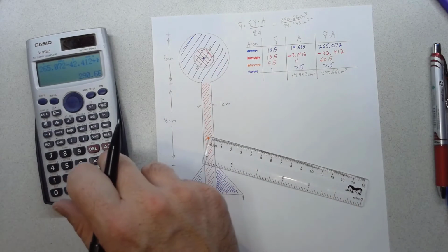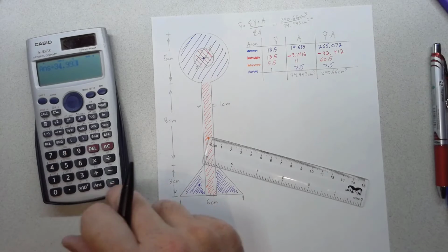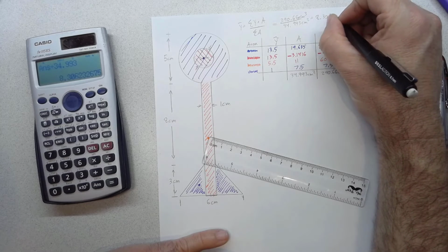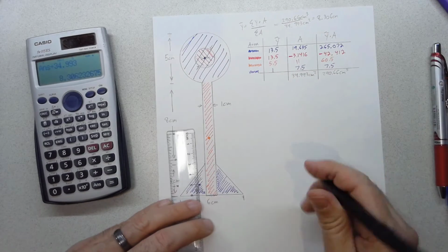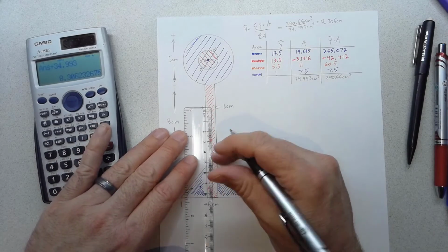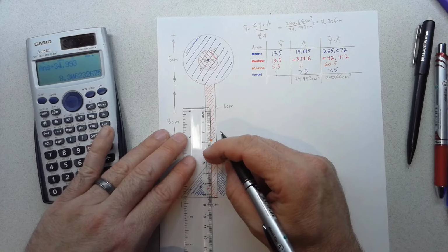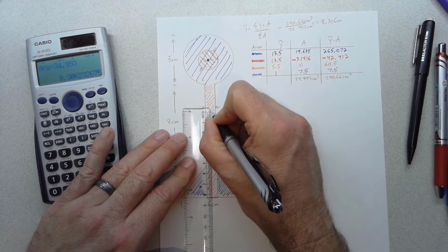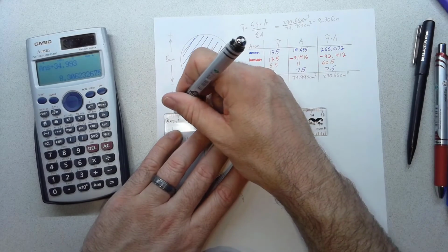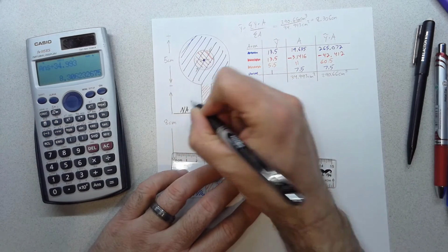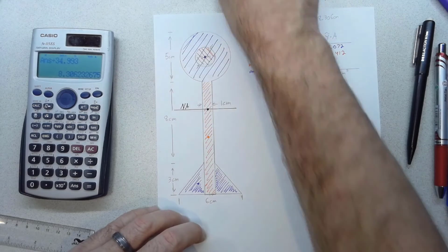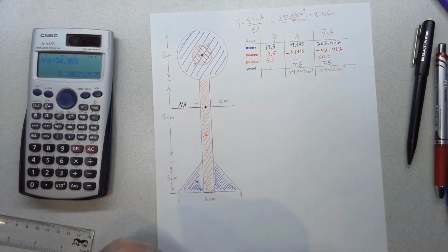We're looking for a length distance, divided by 34.993. So I get my y bar is equal to 8.306 centimeters. So we can measure up for that now and mark our composite centroid at 8.31 centimeters. So 8.3. So right there is my centroid. So this is my neutral axis of this composite shape. Reminder, I had to find that first before I can solve for I, because I is always about the neutral axis. So now let's start looking at the contributions of the individual shapes to I.